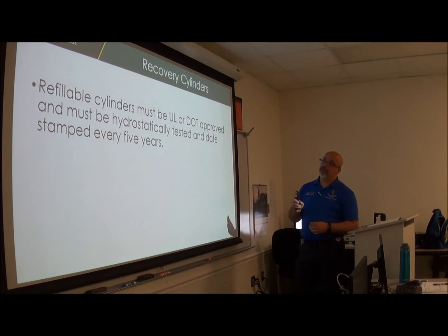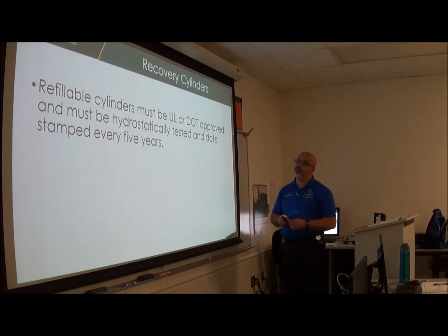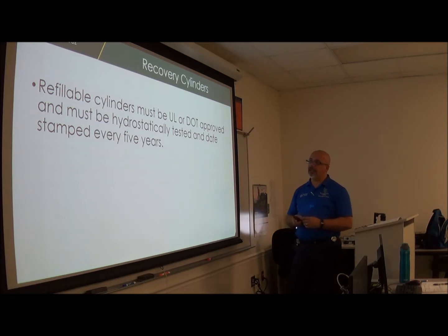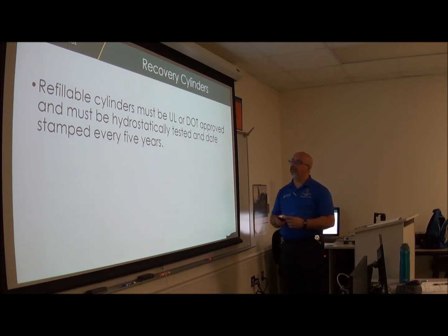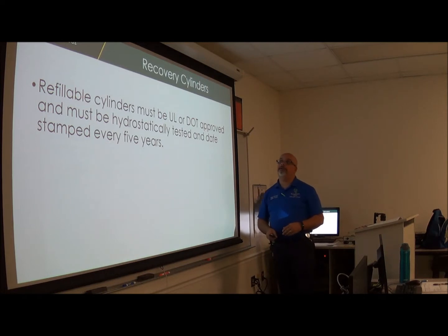Recovery cylinders must be UL or DOT approved and must be hydrostatically tested and date stamped every 5 years. So that's kind of like when you buy the cylinders for your barbecue, they always look at them to see if they're not rusted and all that. It's the same thing here.